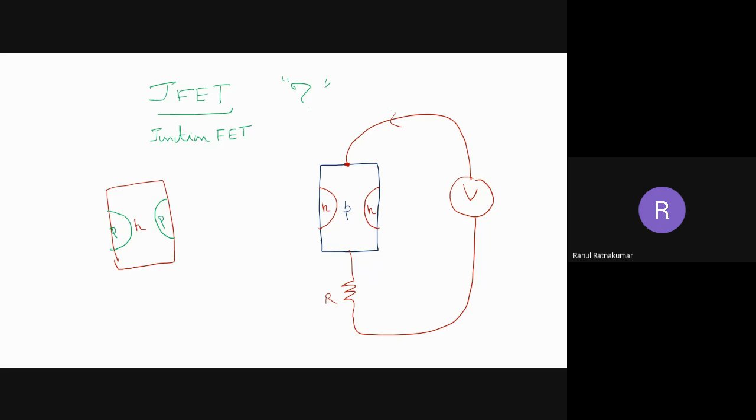You should remember that I'm sandwiching N-type material between P-type material, something like this. Initially the channel is N. I have voltage here, and there will be a current flow, because there are a lot of charge carriers in the N channel. So there will be a current flow even with the resistance. Now this is just like a tank and a pipe. Now how is the control happening?